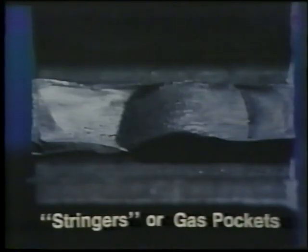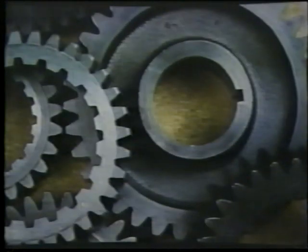Finally, stringers or gas pockets are the result of undetectable flaws or weak points in the metal the gear was made from. These fractures can be identified by the differences in fracture shape and metal texture in the break surface. Again, as with other fractures, it's very important to inspect all gearing in the transmission for possible damage caused by loose particles of metal.